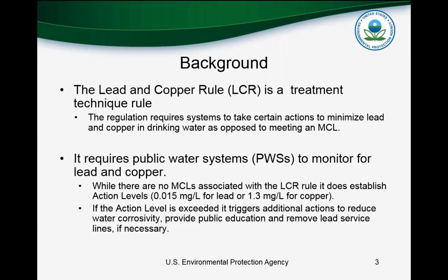So I think, as we all know, the lead and copper rule is a treatment technique rule. It requires systems to take certain actions to minimize lead and copper in drinking water, as opposed to a traditional national primary drinking water regulation where you'd meet an MCL.